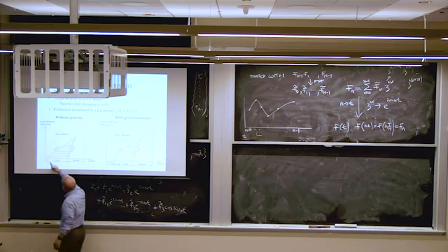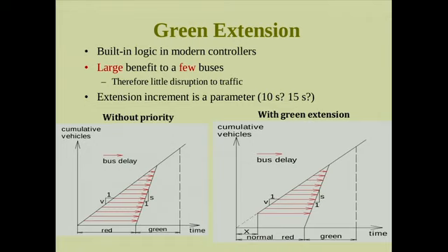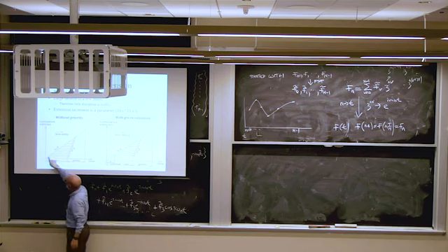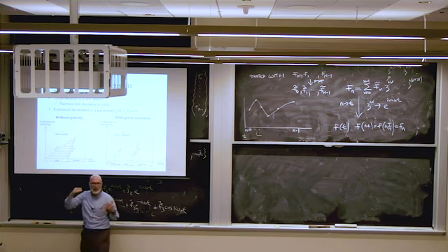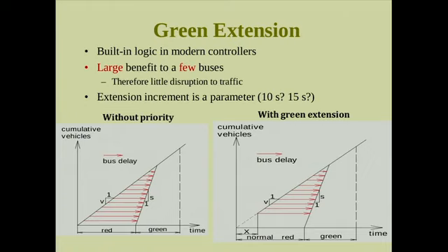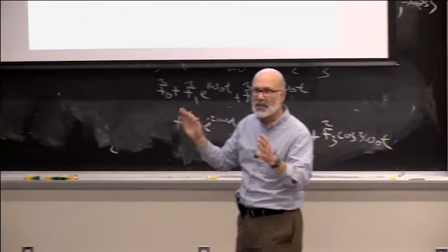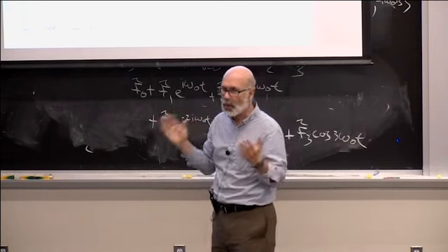So the red lines here represent the time that a person is in the queue. Like the car arrival, here's arrival number 1, and then this line is the departure curve. Cars arrive at a relatively slow rate, let's say 1 car every 5 seconds, and they pull out at a much faster rate, say 1 car every 2 seconds. So each horizontal line represents a certain vehicle that has arrived. Let's say vehicle number 2 arrives here, and doesn't depart until here, so that horizontal line is the waiting time of vehicle number 2. So in this representation, horizontal distance is waiting time.